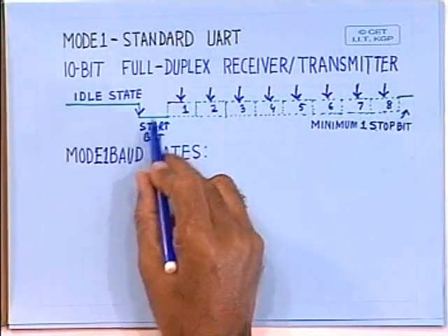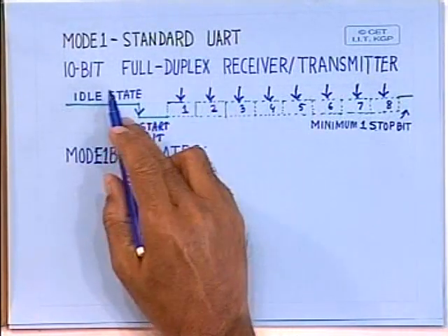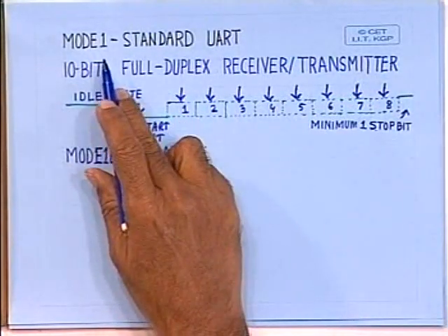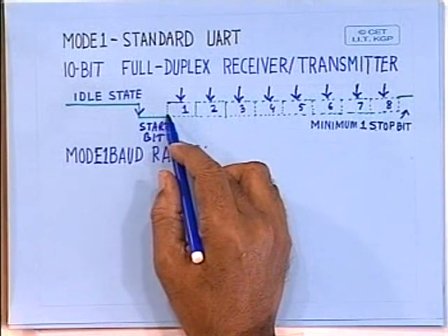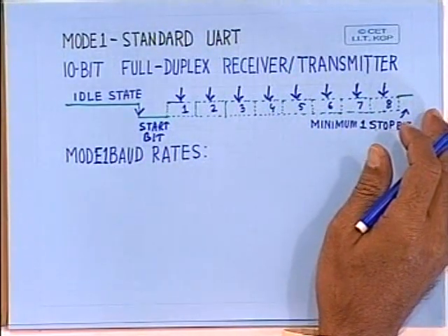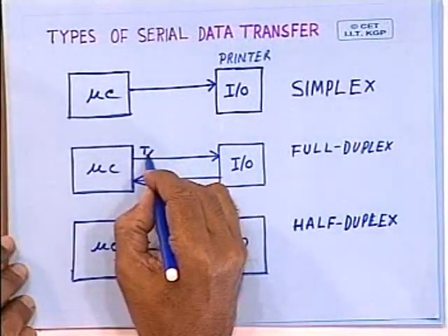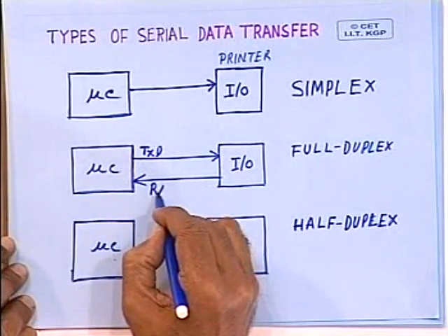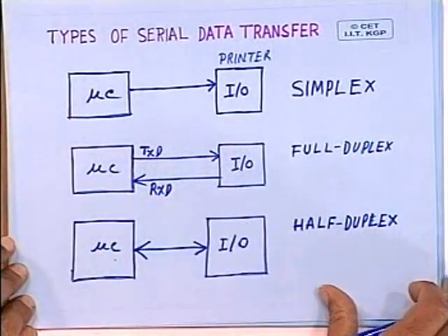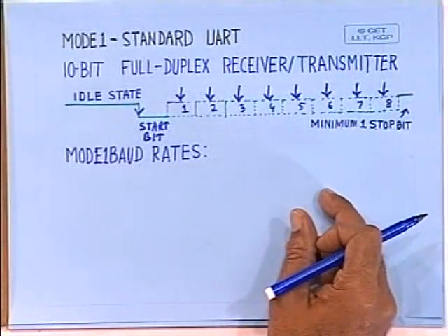So this is how it is being done in serial mode 1, and as I have told, you can use both transmit and receive in parallel, because in this case this microprocessor is provided with the TXD and RXD. Both lines are available for communication in serial mode. So full duplex mode of communication is possible in this case.